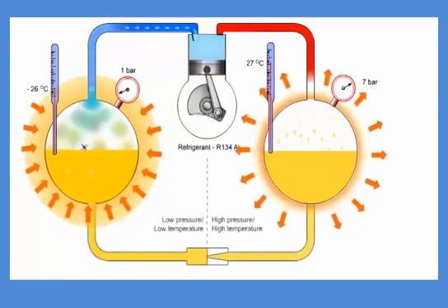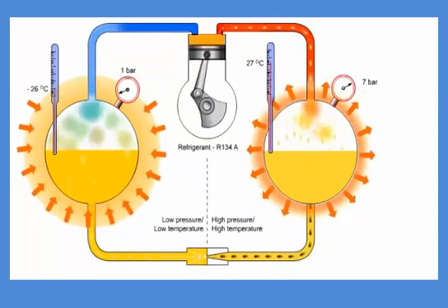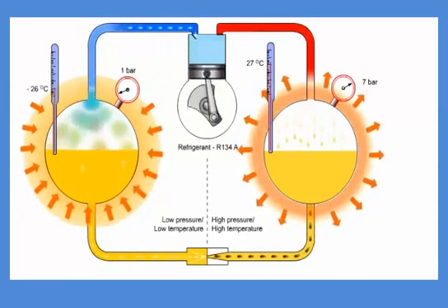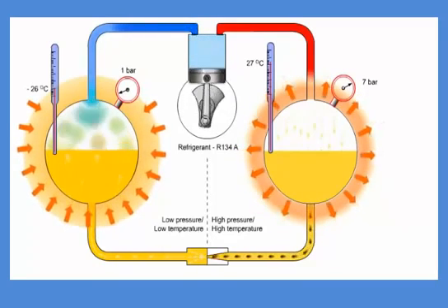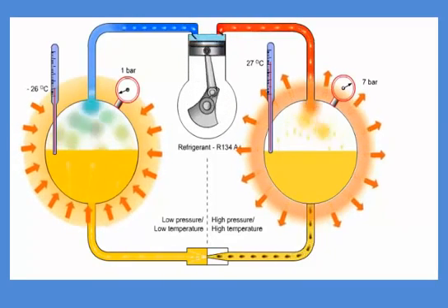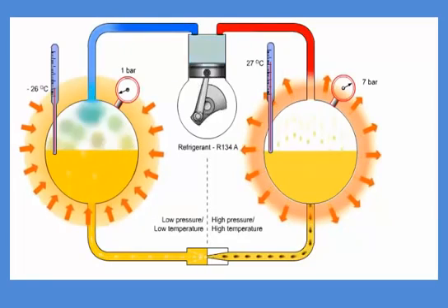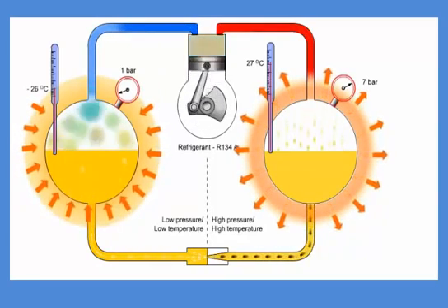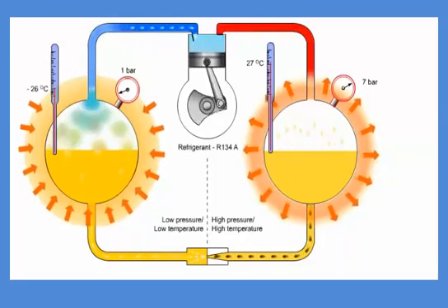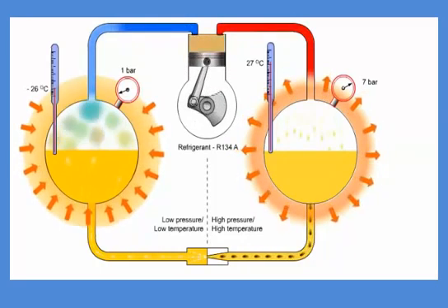Here you see a fourth main component added to the drawing. This expansion device closes the refrigeration circuit and secures that the condensed refrigerant in the condenser flask is returned to the evaporator flask, preventing it from running dry. The expansion device could just be a narrow hole. We call it a nozzle here.